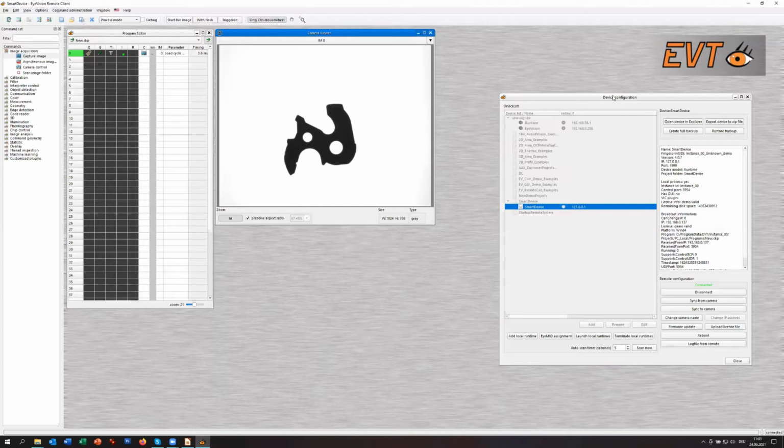If you recapitulate the list we looked at today, these different smart cameras with an x86 or an ARM inside, or one of the embedded systems, all of these systems are much faster than the PCs or machine vision computers used at that time. Therefore, there's no real need now, based on the CPU speed, to say I need a smart camera.